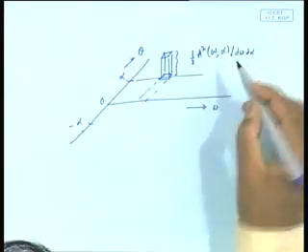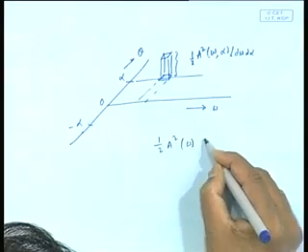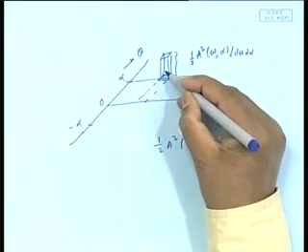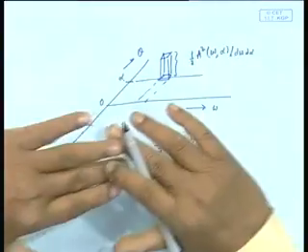See, earlier I did not have this. What earlier I did was put half a square omega divided by d omega. Here I have to put this, because remember the overall volume under this should become the energy. So this is what we mean by describing short crested sea. That means it has a dependence on omega and on theta.